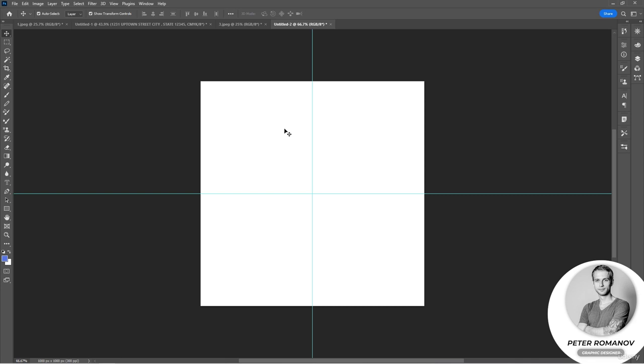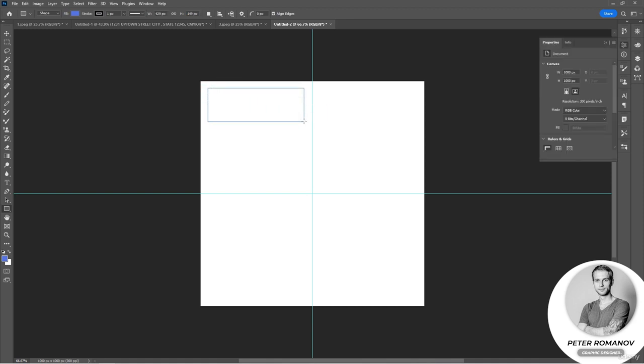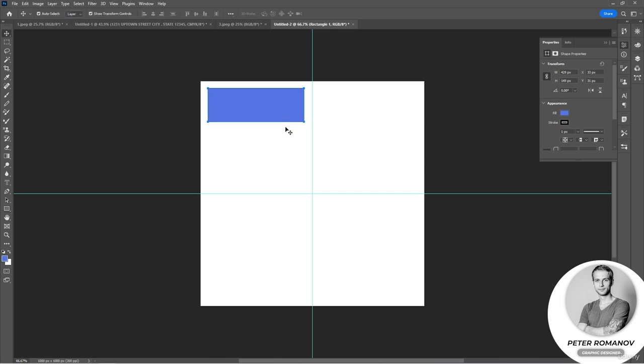There is another interesting feature that allows us to distribute various fragments of our image. For example, let's take a shape that is already familiar to us. I have just drawn a rectangle with rounded edges. These are often used in the website menus. I take the Move tool and press Alt. And look, I drag my rectangle and immediately it aligns vertically and the distance between these blocks is shown. So I can draw one rectangle here, then select, hold down the Alt again, draw the third, maintaining some distance. It may also seem useful to you.